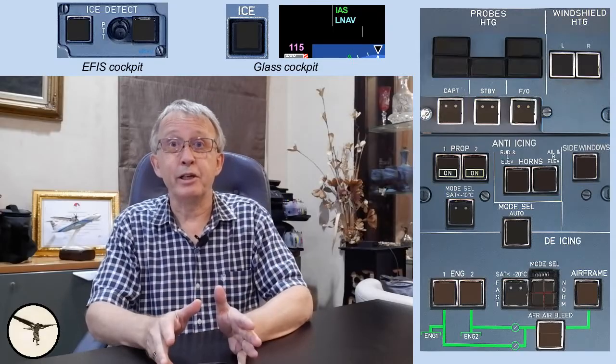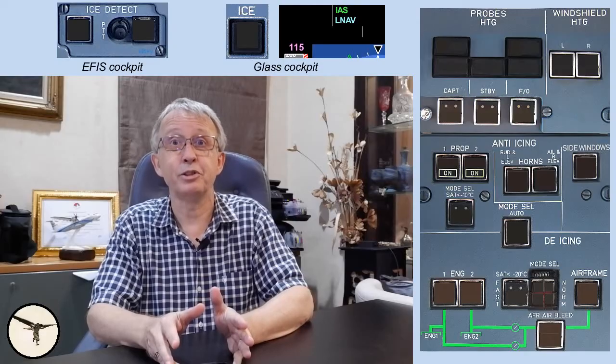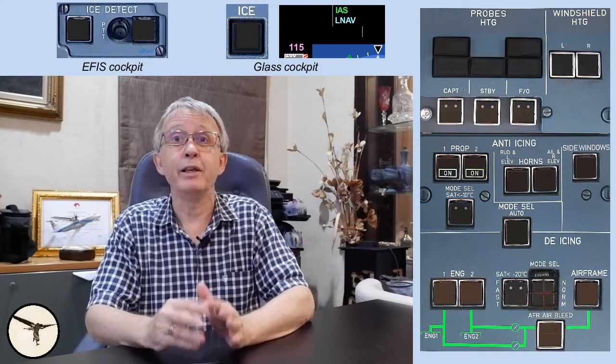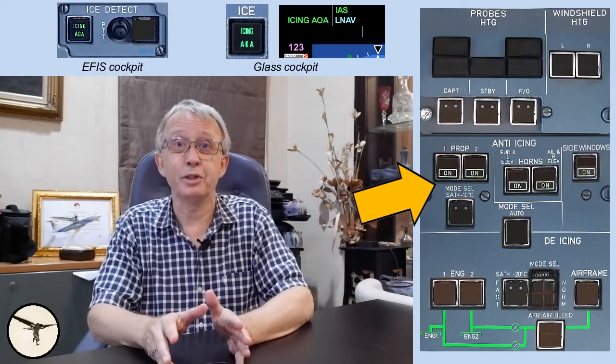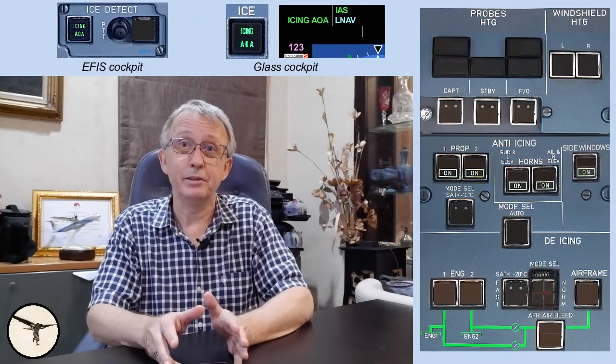If there are atmospheric icing conditions at takeoff, or if we anticipate icing conditions shortly after takeoff, we engage all anti-icing systems and use icing speeds. The icing AV light is now illuminated.